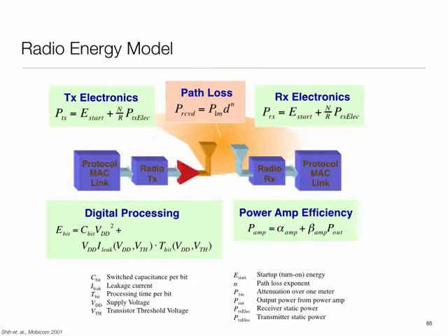Well, okay, so under what condition is d square valid? Free space, okay? Once you are not in free space, then all these reflections, diffractions, and all that kind of thing take place. In fact, if I place two radios with antennas very close to the ground, you can show that approximately the channel is d to the power 4. So if you do not have tall antennas relative to the wavelength, I put two sensor nodes on the ground, okay, they'll actually see a d to the power 4 channel because the ground is reflective of the radio waves at the frequencies we operate at.